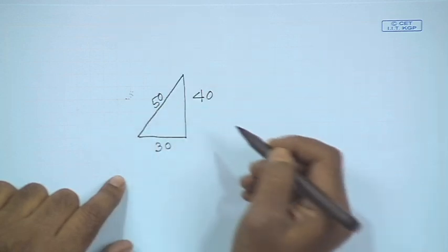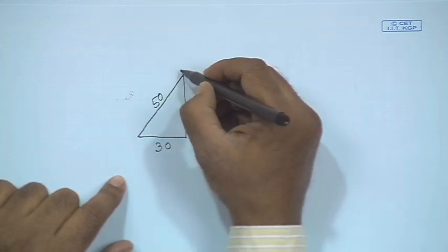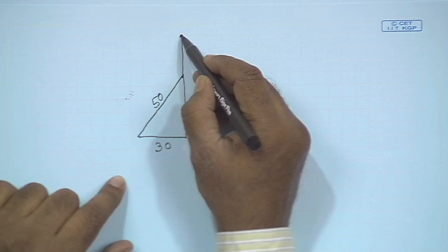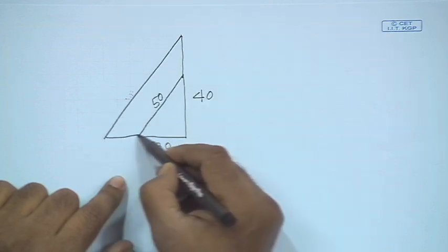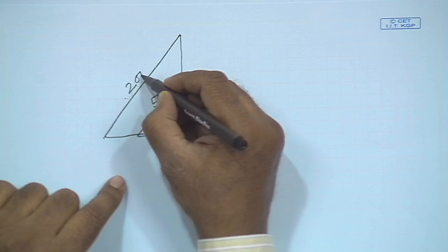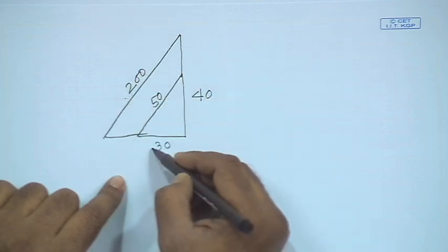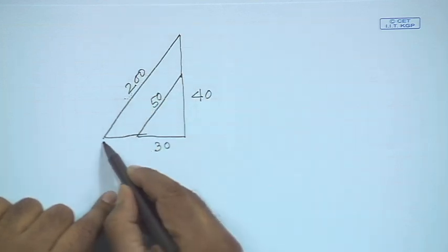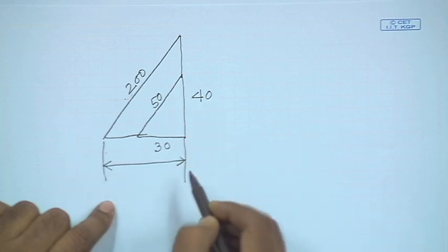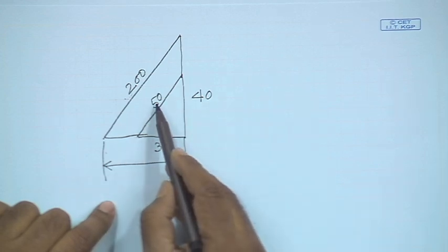This is the displacement triangle, and on top of that we are putting the velocity triangle. What is the velocity triangle? The velocity triangle says that this is 200. So, proportionately, this is the feed along the X axis. How much should this be? If it is 50, it is 30.